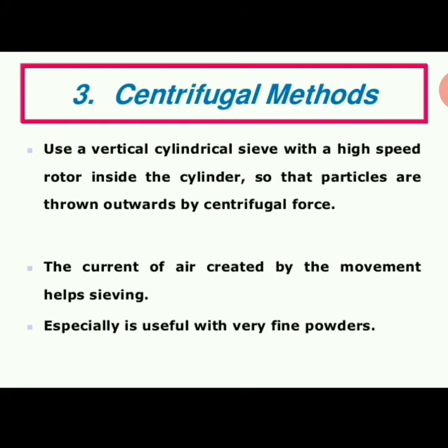अँड दिस सेंट्रिफ्युगल मेथड हॅव advantages. Two advantages are there, such as first is this method is extremely useful in case where conventional sieving tends to block the sieves. म्हणजे काय होईल तर अशा प्रकारच्या मटेरियलमध्ये यूज केलं जाईल की ते मटेरियल सिवला अगेन अँड अगेन ब्लॉक करते. मग जर इन केस जे मटेरियल सिवला अगेन अँड अगेन ब्लॉक करते अशा मटेरियलसाठी सेंट्रिफ्युगल मेथड यूज केली जाईल. म्हणजे ब्रशिंग आणि ॲजिटेशन मेथड अवॉइड करून सेंट्रिफ्युगल मेथड यूज केली जाईल.